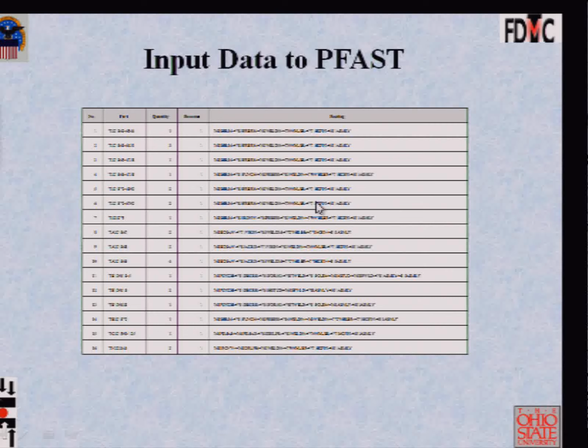So that is the beauty of the value network mapping, that you know which identical routings can be merged and put on top of each other. Just put all the part numbers beside them. But you also know a part family. That means you know which value streams are similar, so you can create a flexible cell to produce all of them, but you retain the identity of those value streams which are not identical. Okay?